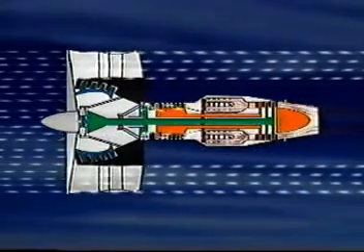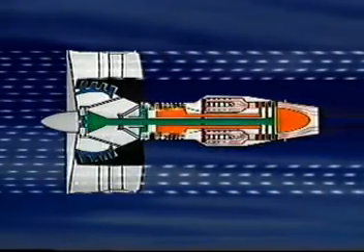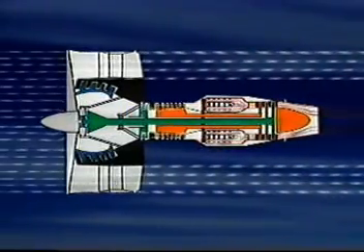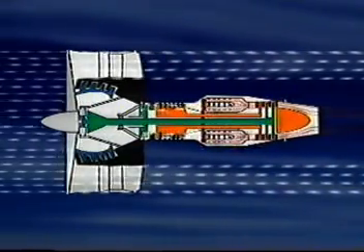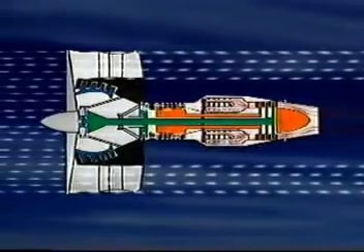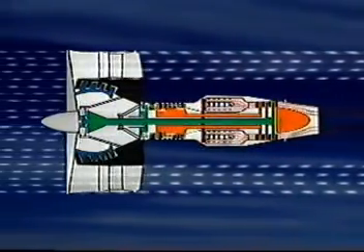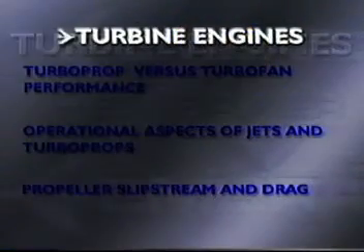In the Embraer regional jets, the air leaving the fan surrounds the engine for its full length, and it is discharged through the jet nozzle. In other turbofan configurations, you might find engines with short ducts, where the fan air is exhausted directly into the air, without being mixed with the nozzle air. Now, leaving the turbojet engine aside, let's compare the performance of the turboprop and turbofan engines.